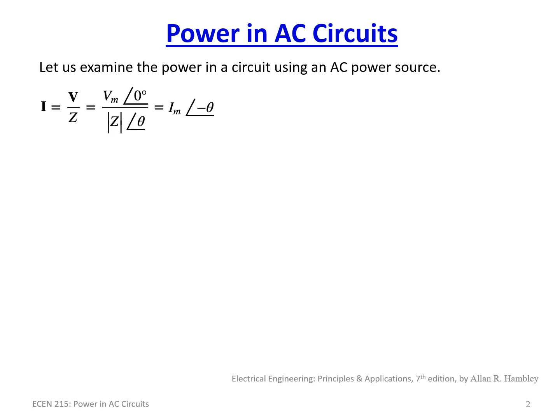Obviously, Ohm's law still applies, everything that we're doing. Current is voltage divided by the impedance. Here we have voltage magnitude of phase angle of 0 at some frequency, some radians per second, divided by the magnitude of the impedance and the phase angle of the impedance. And because of the division, we get Im, which is Vm over the magnitude of Z, with 0 minus the phase angle. So there's a lagging component here.